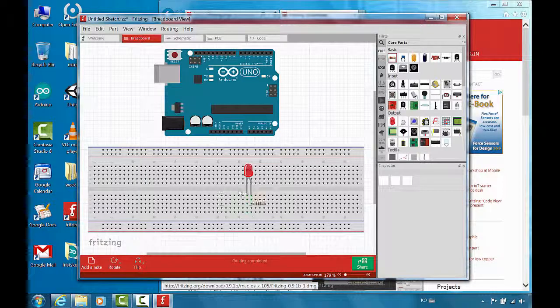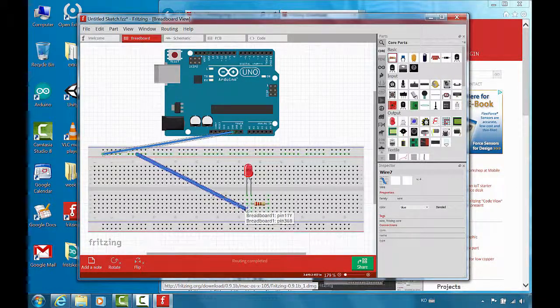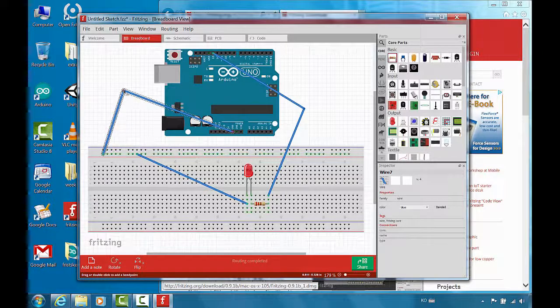Let's connect the microcontroller and the LED. First, I'm gonna connect the ground to one of these breadboard lines. Once you do that, the green color indicates potential connections, and one of these we can connect with this LED. The ground is negative, and this one is positive. The positive in this case needs to go to pin 13. If you want to add an anchor point to this wire, you just click and drag. You can add the anchor point.